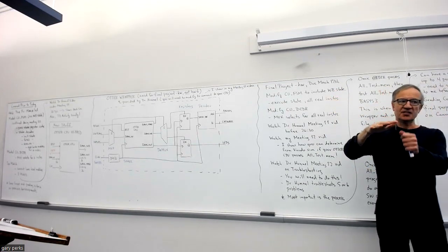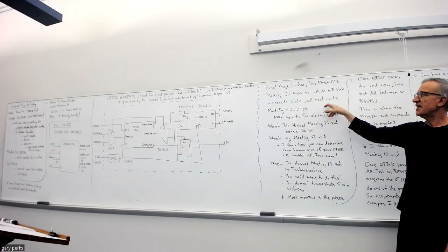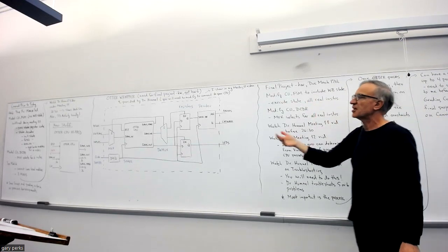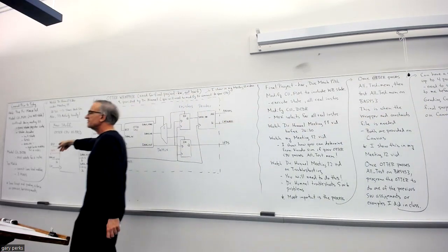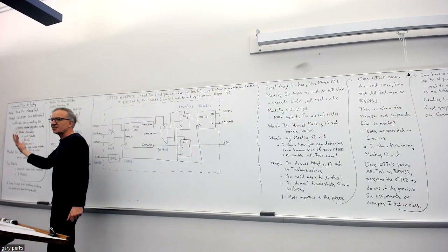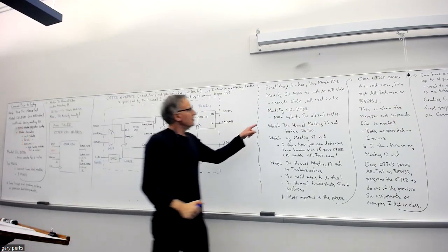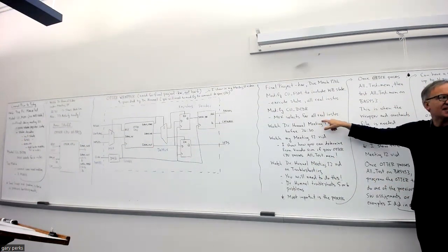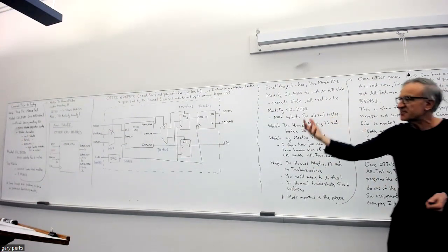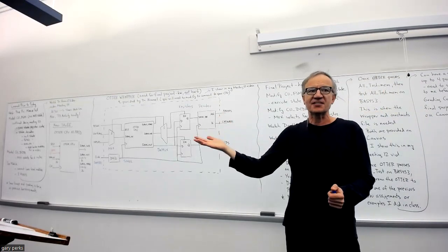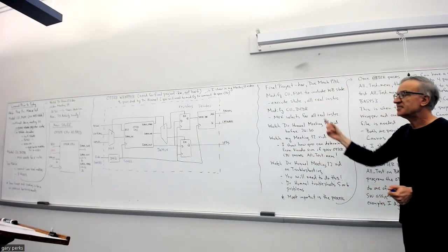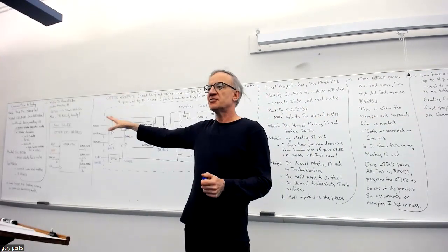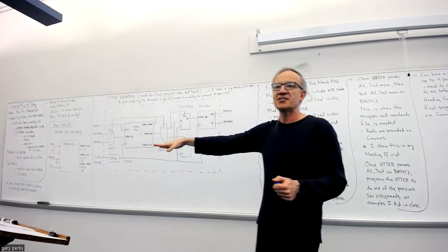Also, you're going to have more code in the execute state of the state decoder for your FSM, right? Because now every instruction, you have to tell it to read and write in 8 instead of just 6. For your control unit decoder, you're going to have to add stuff, right? Because now you need all the mux selects for every instruction, not just the 6. Okay, but like I said earlier, you're not going to have to touch the top module. If your top module is good for hardware 6, it's good for the final project.